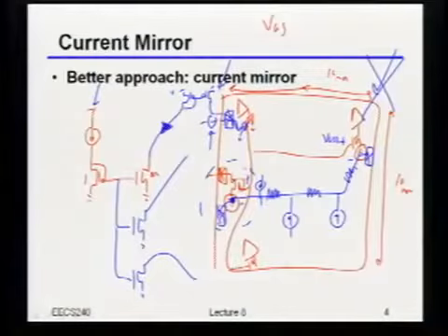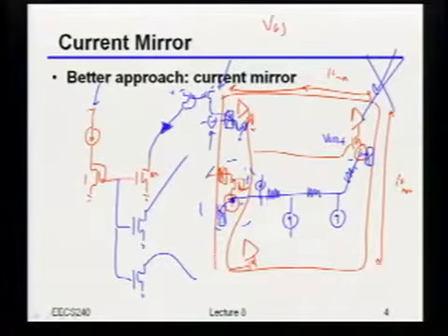You still have some pretty long antennas, if you were to try to do this. So you're saying, okay, I do this whole trick, but at some point I'm going to have to distribute a voltage somewhere. You're absolutely right. But if I make that wire short enough, I know very well what the voltage drop across the ground should end up being. And in fact, in some of the really careful analog designs, there are even ways you can route that ground wire to make sure you know exactly what the IR drop will be, or that it doesn't cause any error inside of a small local unit. The problem is when you go over the whole chip and you don't know what the whole chip is doing, then you can really get some big errors.